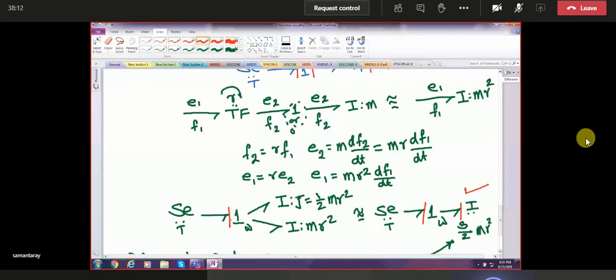So most often we see that you can always get free rolling, even with this model, by making this frictional resistance very high. If you make this frictional resistance tending to infinity, then what will happen? Whatever be the difference between these two forces, the slip will tend to zero. It will not be zero, it will tend to zero, and you will get pure rolling. Alright? So it's always better to maintain this resistance in the model and vary its parameter.